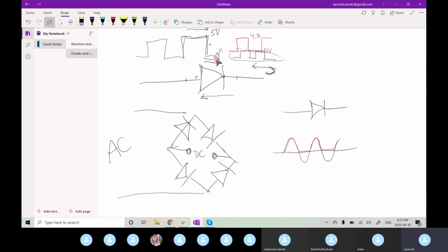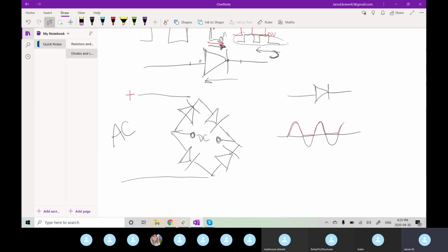So in the case of the rectifier, when it's on its positive half cycle, pumping current in, you'll see current properly come across, and then it gets blocked by this diode. So it comes across your DC load, then the signal path, and over to ground, and completes the path.